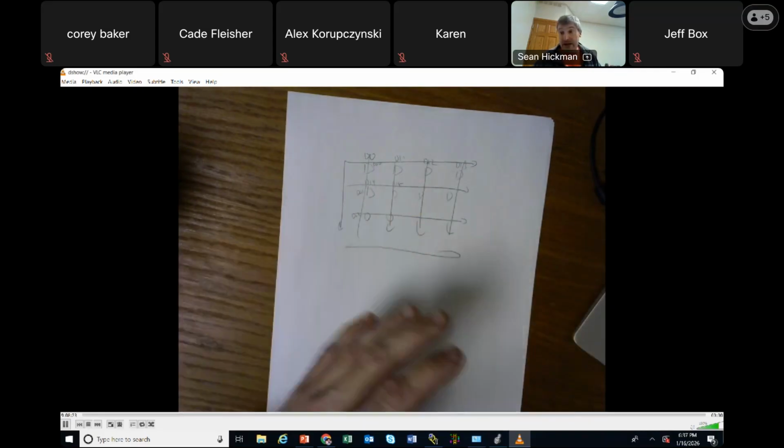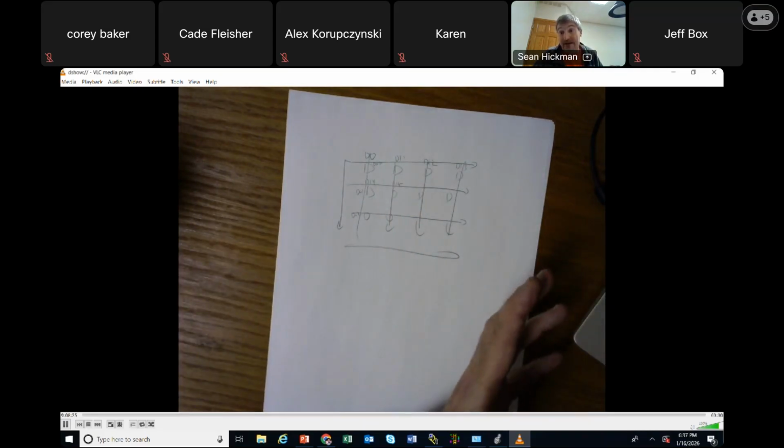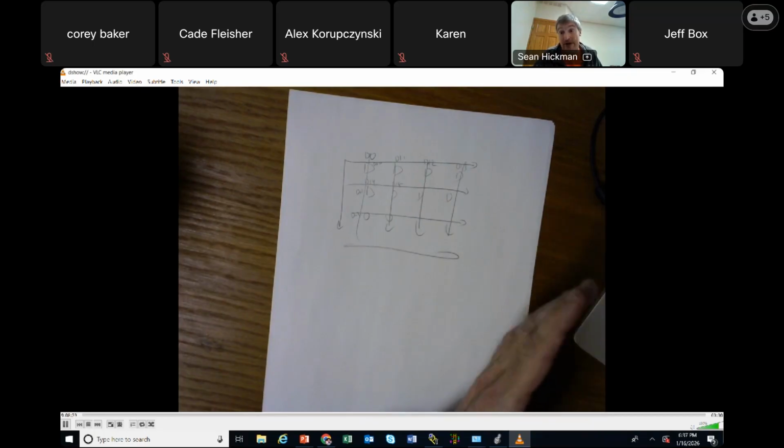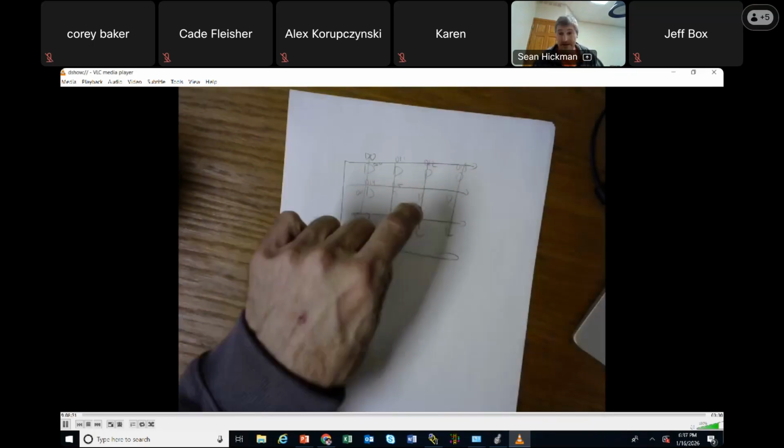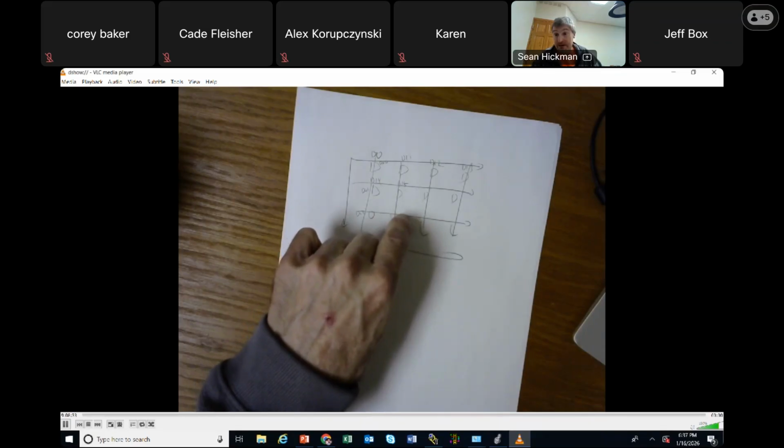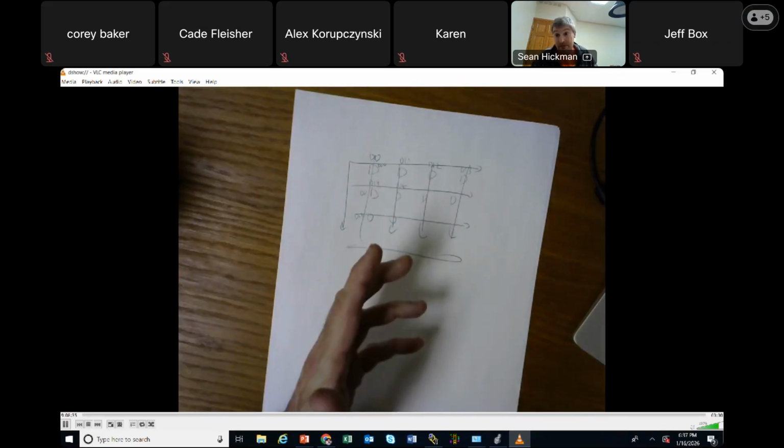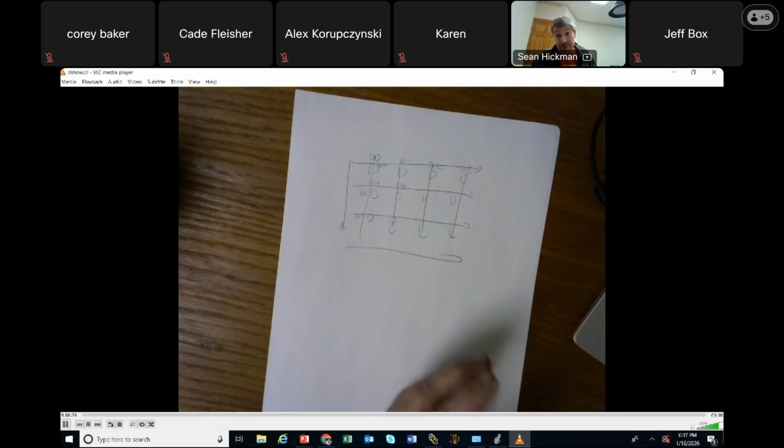But you have to understand, it's just a lighted push button where the push button and the light have nothing to do with each other. They're just wired into the input modules and the output modules. Does that make sense when I say that it's a lighted push button and half of it's an input and half of it's an output, and they have nothing to do with each other? Does that make sense on a scale of 1 to 10?